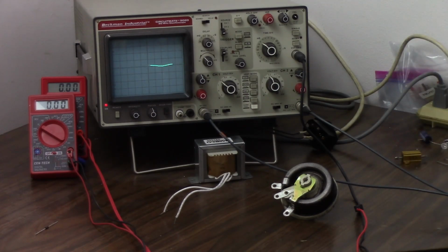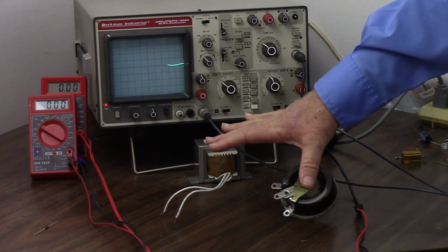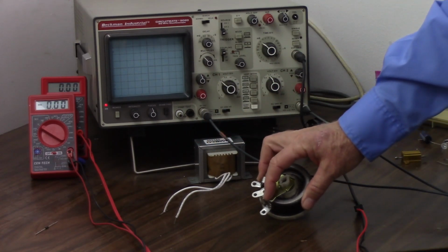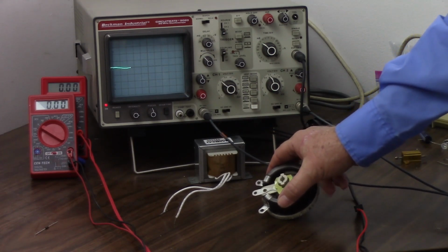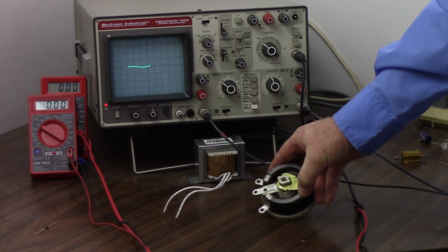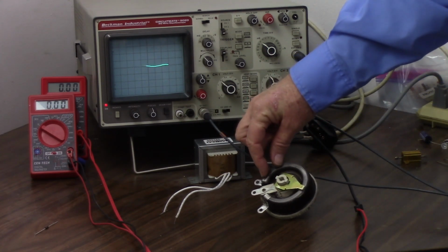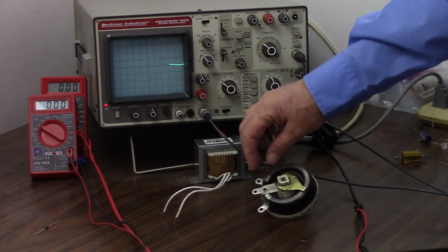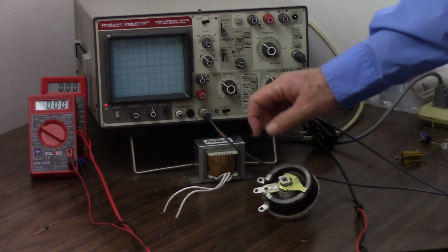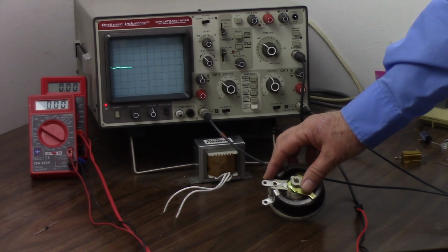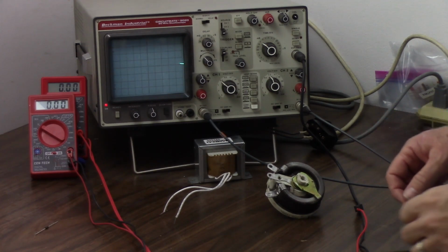So what can I do? Well, it's pretty simple. I can just go ahead and set it up without a current meter, and I will adjust this rheostat, not even caring what resistance it is, until my voltage drops down below a peak of 14 volts, and then I will measure the resistance. Knowing the resistance and the voltage, a peak of 14 volts and whatever resistance I have here, I can divide that resistance into my voltage, and that will tell me how much current I was getting. So let's go ahead and do this.